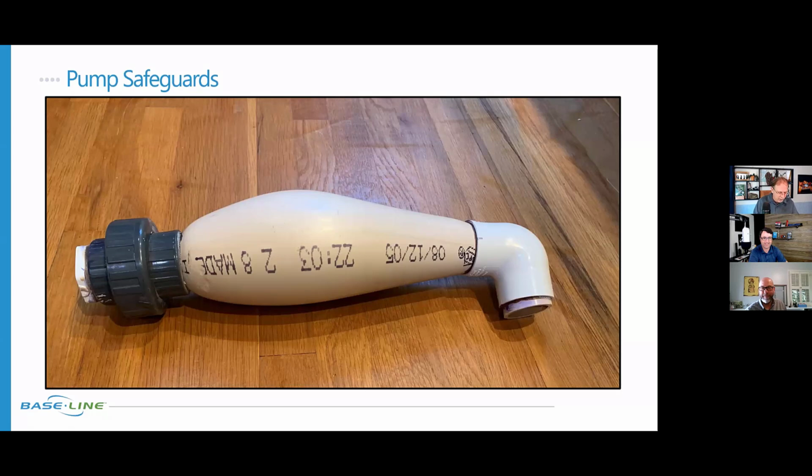Well, how do we get those pump controls on our simple pump system? Well, we can do that with our pressure component. We can do a start, stop, or pause condition and control a pump based off of it. Allow a pump to start if the pressure is at a certain level, or stop it or pause the pump if the pressure is at a certain level. So we can get some very similar pump controls out of that sophisticated pump package on our old pump system.